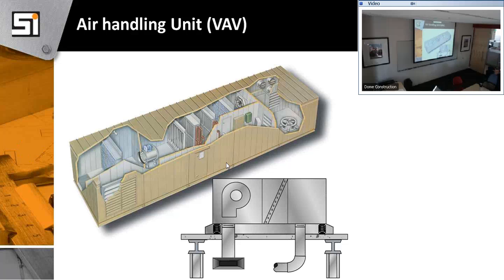I talked about a VAV and a minimum. In the old days I had to stop at 500 CFM and start reheating. Now I could take it down to 150 and reheat there, so that's the savings. And if I was in a cooling mode, I was going to have to cool that 500, spending mechanical energy to cool it just to come in here and reheat it. So yeah, the July 1 Title 24 is locking all of that up. Everything's about energy, and there are some changes on that.